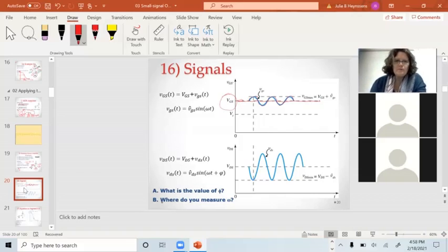Different nomenclature people use is, well, of course, this silly equation we've already been over with all the case changes. Now, our signal voltage, our little vgs, is a function of time. It equals some peak magnitude voltage, and that's what the little hat means, the peak voltage, times the sine of omega t, if it's just a simple sinusoidal signal.